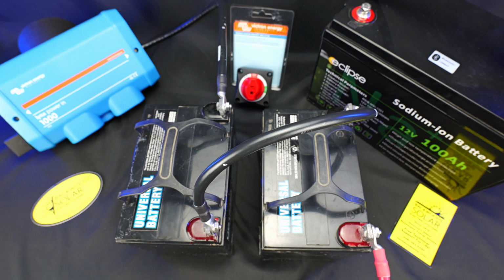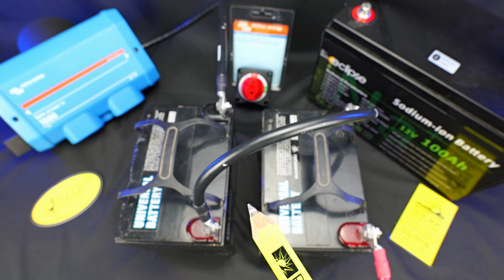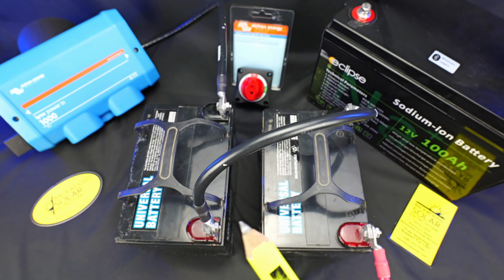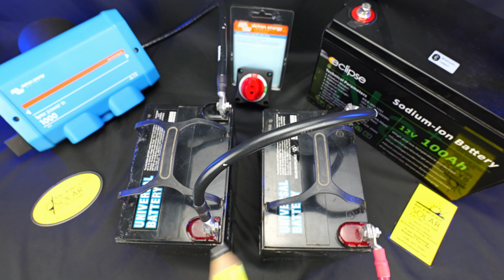With lead acid, we have a little bit more leeway with that as they're not as low resistance, so slight differences in resistance between strings or batteries isn't as noticeable as it would be with lithium, but still good wiring practice to have equal lengths and equal diameters.